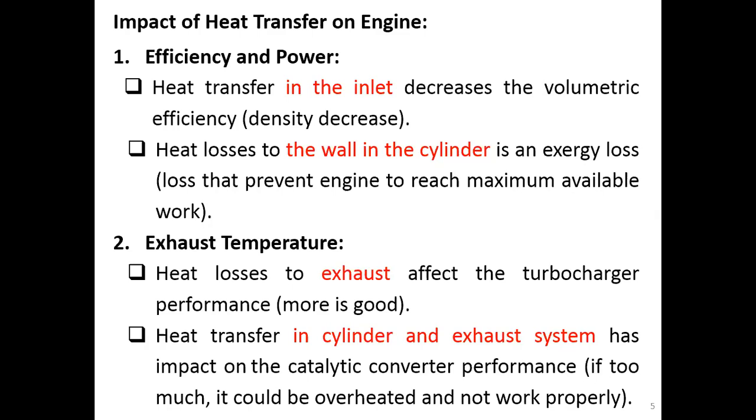The catalytic converter is the device that reduces the emissions that come out from the engine. We will talk about this more in our next lectures. So if you have higher heat, the performance of the catalytic converter is going to be bad, because this equipment could be overheated and will not work properly.